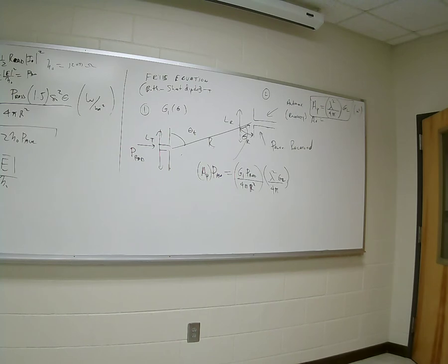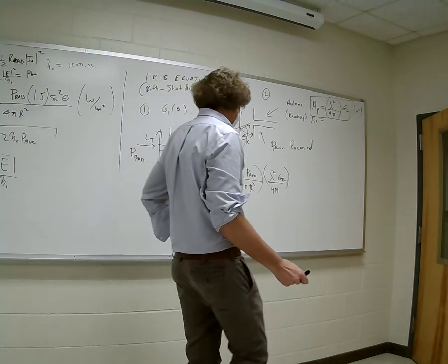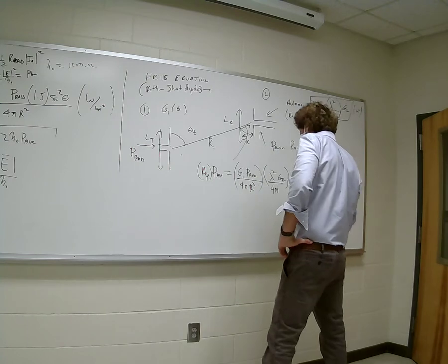Maybe I did put it somewhere. Yeah, I did, but I'm going to put it here. The gain itself for a short dipole is 1.5 times the sine squared of the angle theta. And theta is always measured from the axis the antenna is on to the radius vector r. It's real important you get that. It's a sine squared.